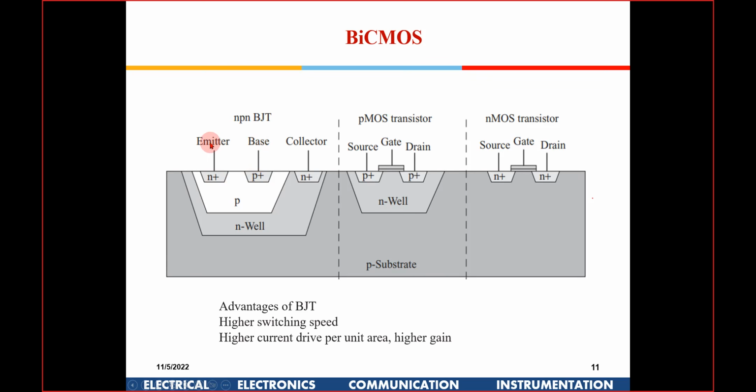So that is why you have IE equal to IB plus IC, right? So essentially the collector current is a function of the base voltage you apply. If you apply more base voltage, more electrons will be pulled from the emitter. A small portion of that will go to the base, but a larger portion will go to the collector.